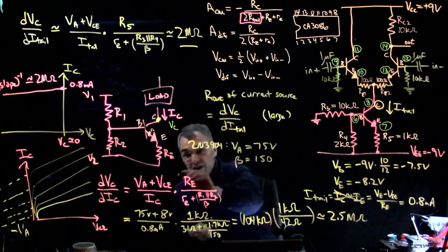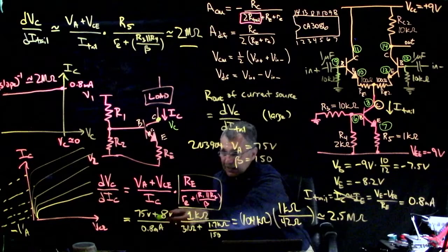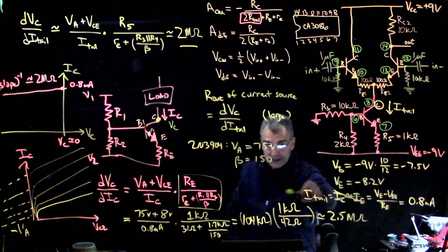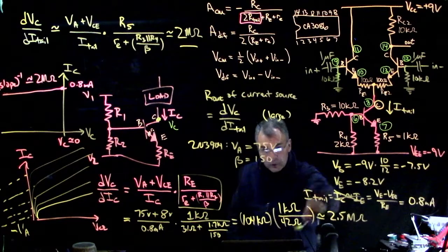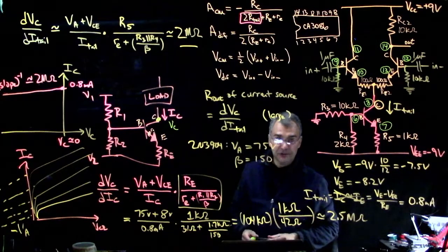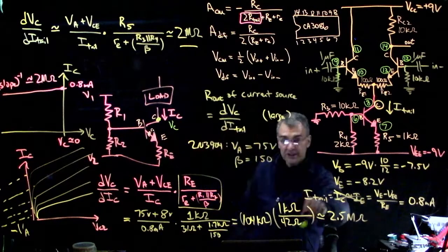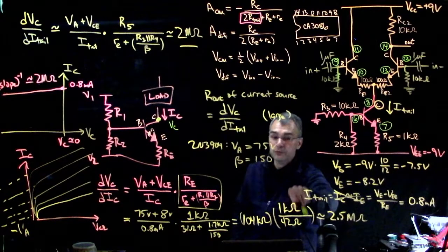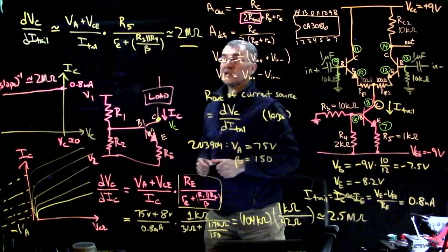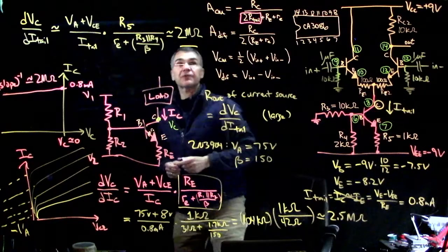And so the result of that feedback mechanism is that we have taken this left-hand factor, which is like 100 kilo ohms-ish, and we've multiplied it by this factor, which is what, 20, 25-ish. So that's kind of cool. Yeah. So the presence of this emitter resistor is basically what gives us this factor of 20 or 25 improvement here in the reciprocal slope of this curve. Whoa, okay, that was a long digression. Good grief, that was a long digression.